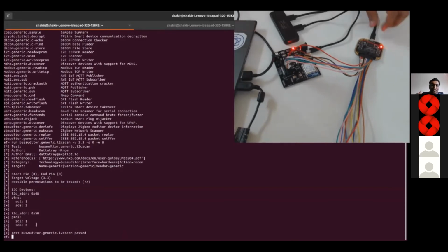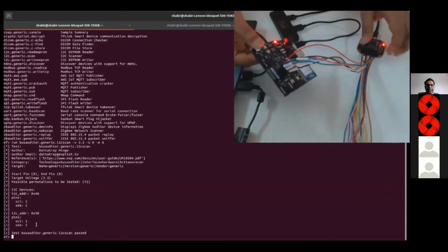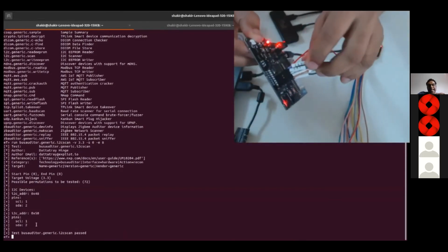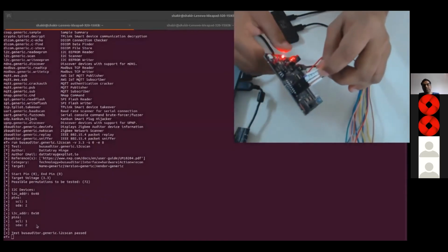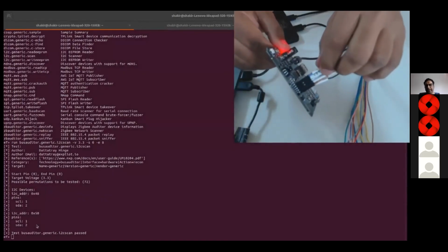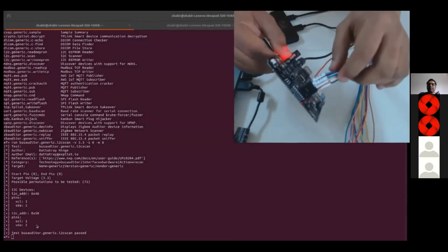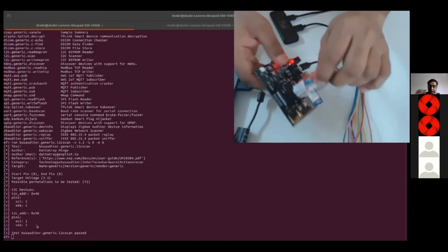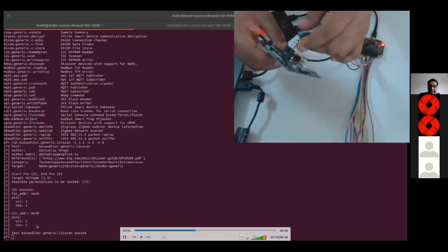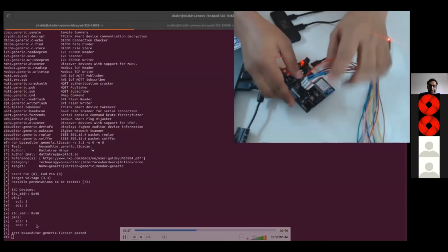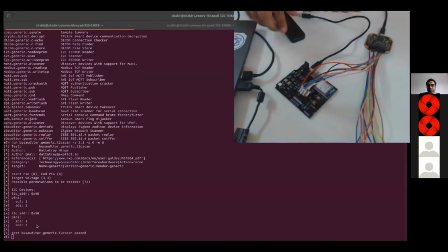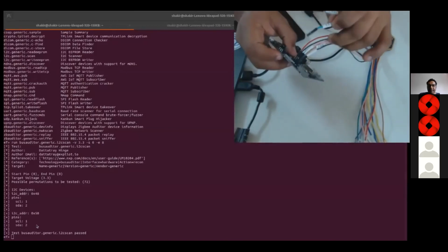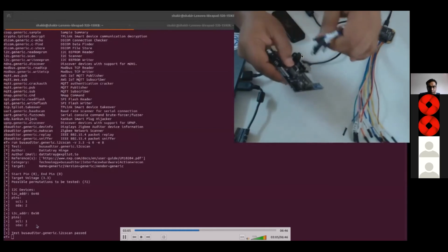Now, once we identify this device, the next part is to attack it. We want to extract some information, some credentials let us say, from that. So now the job of the bus auditor is done. We first have to identify which pins are connected to pin number 1 and 2. That's what he's showing over there. So you identify which pins are 1 and 2 physically on that particular board.